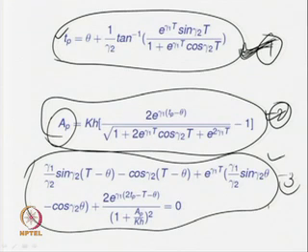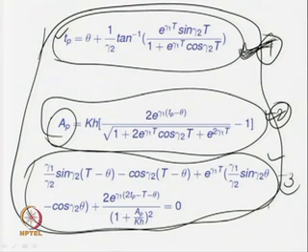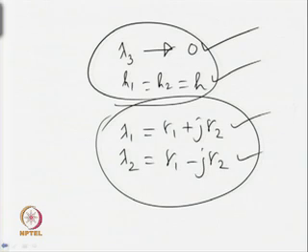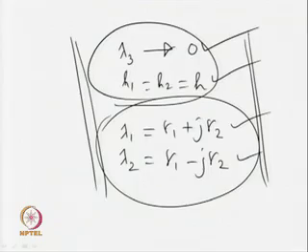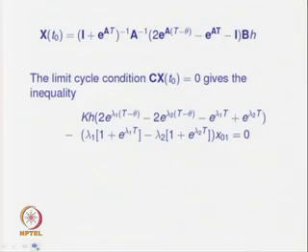So, you can try and derive it, these are not difficult. As I have told, you only need to substitute the limiting values in those expressions, and you do find these simpler expressions 1, 2 and 3, which can be used for identification of underdamped second order plus dead time transfer function models. So, with this I will go to the simulation examples.